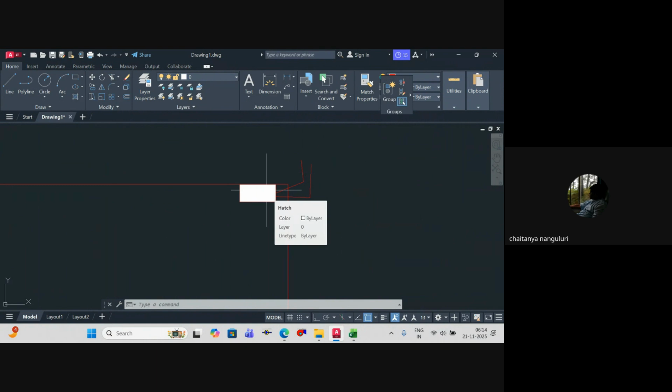That means whenever you're working on projects as per NBC code or as per NFPA codes also, your emergency door should not be locked. Obviously, right? In case of fire, if it is locked, let's say, access control might not work or the key might not turn. Is it okay to have it like that?